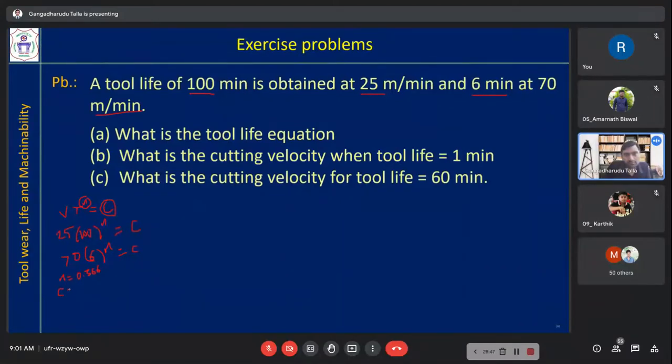C equal to 134.8. So once you get any value, generally you think about its range so that you will come to know. Generally, n varies from somewhere 0.1 to 0.5 in that range for any material. We have seen that list for different materials also. So it is within the range, which means our method is fine. This is a simple thing only.